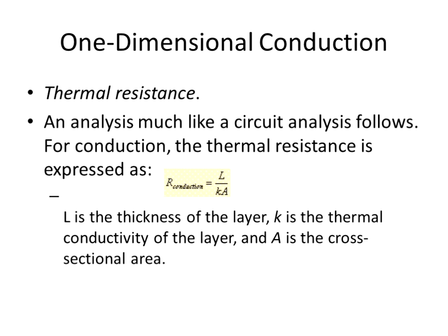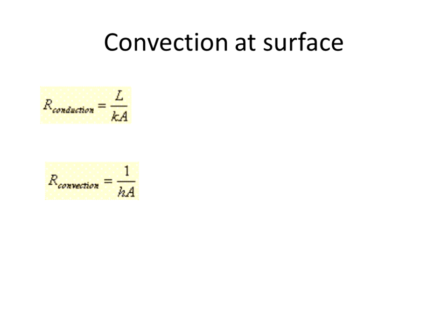So the thermal resistance, and this is for conduction, okay, would be L over K A, where L is the thickness layer, and this L is what we had called earlier delta X. K is the thermal conductivity, and A is the cross-sectional area. So all of this is the same concept, just they call it differently for some reason. So this is the thermal resistance due to conduction. Okay? Whenever we have convection, then we also have a resistance, and it's 1 over HA.